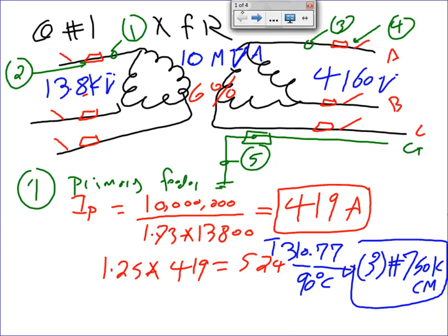Every system has a grounding with it, but not every system is grounded. When they ask you, is this a grounded system, it means, is the transformer grounded on either side? No, it's a delta. It's not grounded. What does grounded mean? You take one from the gut of the transformer to Mother Earth. Look at all the windings. Am I grounding any of the windings? No. That's an ungrounded system.